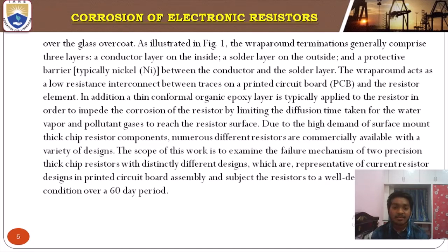In addition, a thin conformal organic epoxy layer is typically applied to the resistor in order to impede corrosion by limiting the diffusion time taken for water vapor and pollutant gases to reach the resistor surface. Due to high demand for surface mount thick chip resistor components, numerous different resistors are commercially available with a variety of designs. The scope of this work is to examine the failure mechanism of two precision thick chip resistors with distinctly different designs, which are representative of current resistor designs in printed circuit board (PCB) assembly, and subject the resistors to a well-defined corrosive condition over a 60-day period.